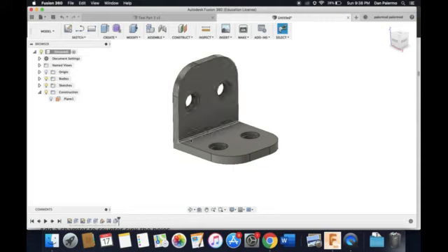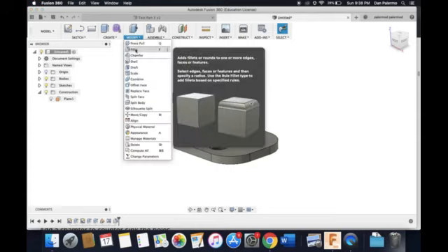The reason why you would put a fillet here, guys, is if this is a bracket that's hanging on a wall of some sort, where something's hanging from this portion, this part will likely fail right here. That's where it would crack or fail. So we need to strengthen this part. And the way we're going to strengthen it is we are going to place a fillet.